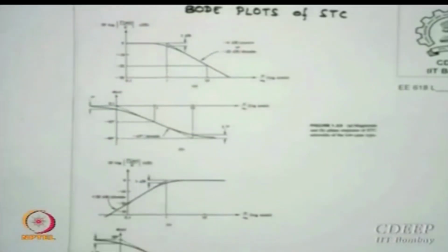But for some reason, if you do some mischief by putting some capacitor or other resistors around, this can show a high pass filter frequency even at the lower side. Coupling capacitors at times force you into a high frequency pass system, and therefore you may see even in op-amps, which are called AC coupled op-amps, a normal mid-band gain with fall on both sides. So please remember, Bode plot and frequency response are no different.